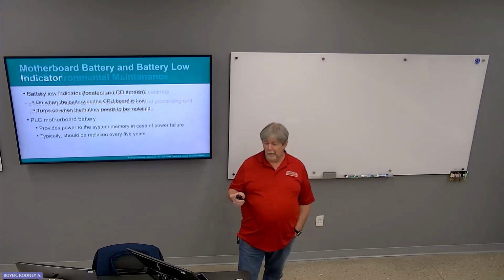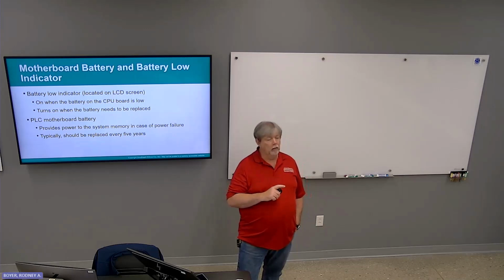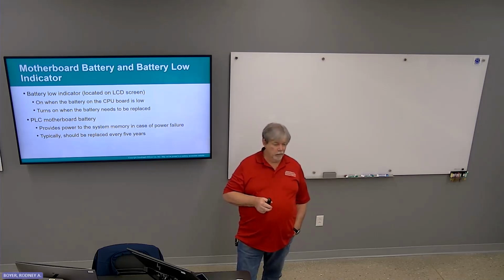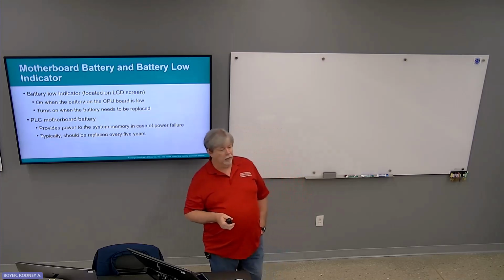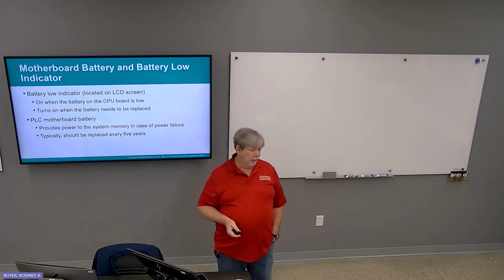One important thing about the battery: you must leave the power on the controller when you disconnect the battery. If you have the power turned off and you disconnect the battery, you will lose the user program. So always make sure you have the controller power on before you disconnect the battery to replace it. So you don't have to break out the laptop and reload.